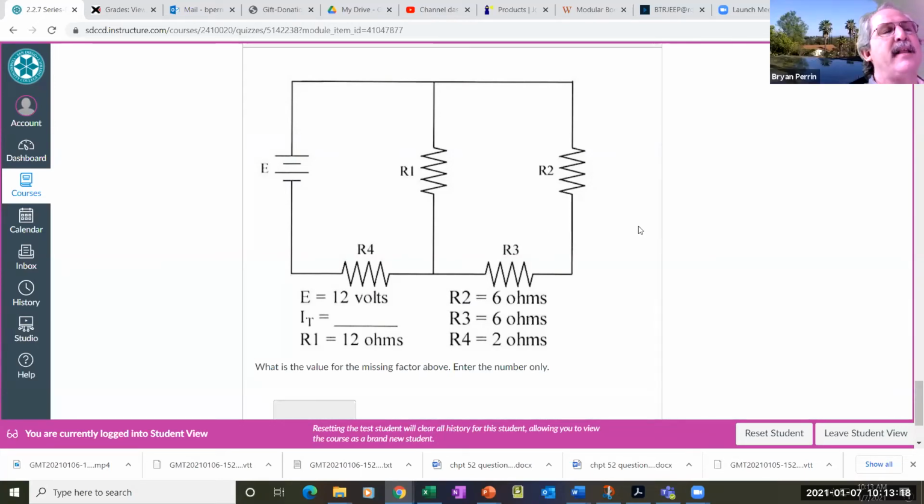No, see, that's great you said that, because this goes back to what I talked about, what we need in a circuit. I need a power supply, conductors, and a load. So I start with a power supply, I have my conductors, a load, and I get back to my power supply. I got my conductors, 1, 2 loads, and back to my power supply. Now, both of these circuits share this, so I can treat this as part of my power supply.